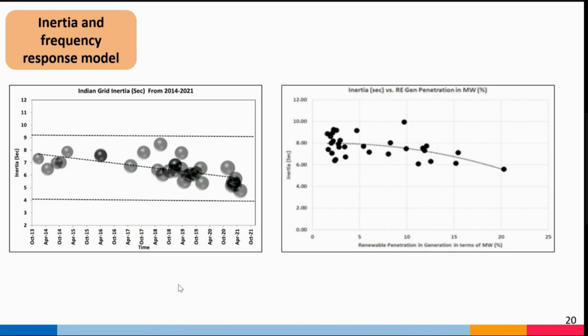You have multiple PMUs placed in the entire power system, so you have frequencies available from geographically spaced locations. Based on that you can isolate, removing the frequencies which have higher oscillation, and you will see a smooth fall in frequency in certain PMUs.